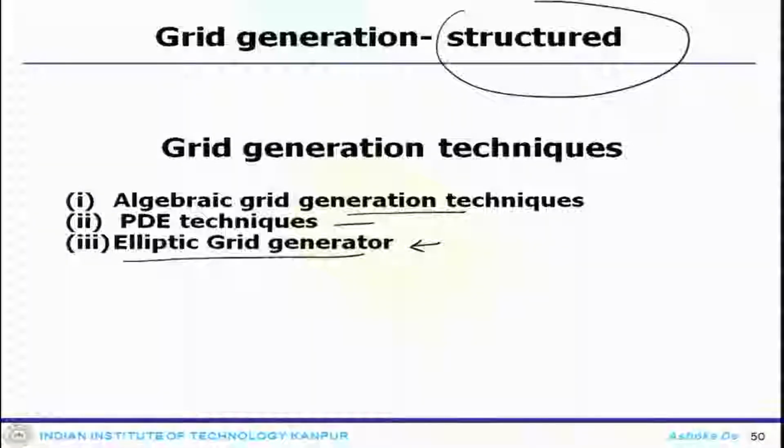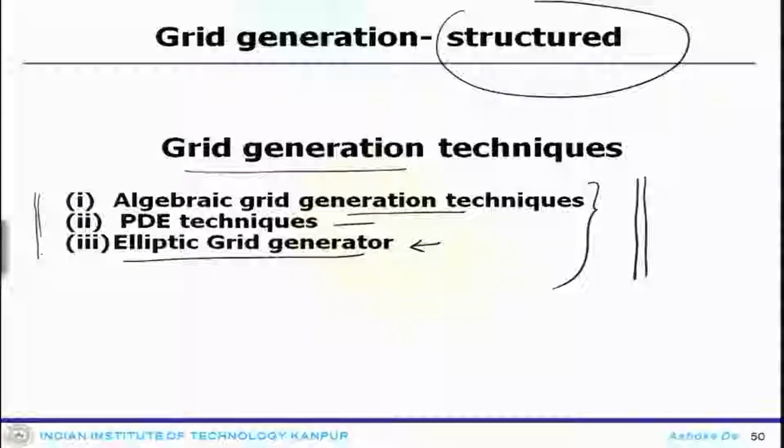So, these are the different standard techniques available, and these days there are a lot of commercial software packages dedicated to grid generation, and as per the requirement of your code you can generate the grid with one of these techniques. But it is very important to know how those commercial packages actually work. Behind their graphical user interface, they solve one of these kinds of techniques, whether it is an algebraic fit, a partial differential equation, or elliptic.